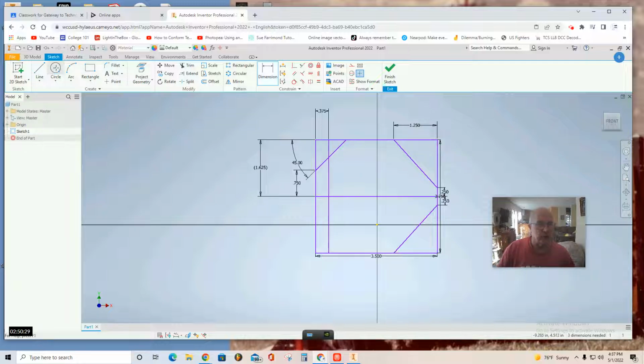Now I'm going to use a circle tool, and right on this line segment, click, I'm going to draw a circle. As I drag it out, I let go, I type 0.25 for the diameter. Enter, and I can place another circle here like that too as well.